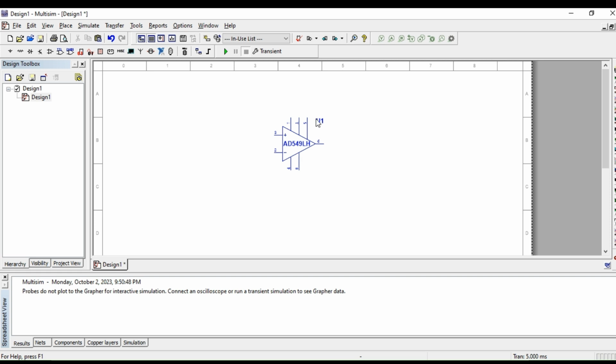For instance, if this voltage amplifier is connected to a power supply of, let's say, plus minus 12 volt DC, then ideally the maximum voltage cannot go beyond positive 12 volt or below minus 12 volt. But practically, the voltage peaks should also be lower than these ideal values.